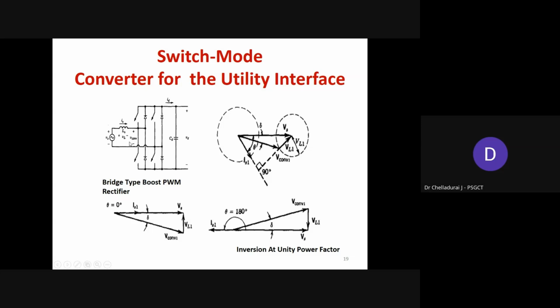And at the same time, we can exchange the power from AC to DC or DC to AC. So again, in this vector diagram, it is unity power factor operation. Second case, again, unity power factor operation, but opposite direction. So simply here, the inverter, especially the VSI inverter, can be operated in 4 quadrants, simply by varying the voltage magnitude